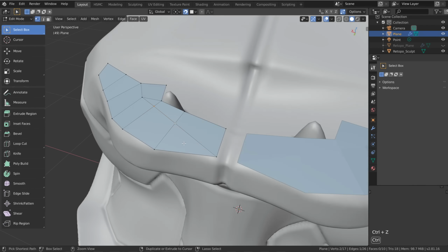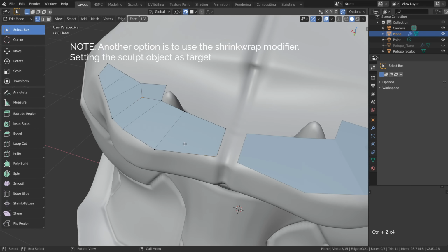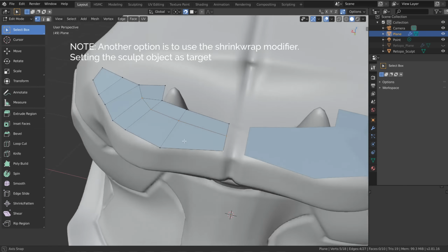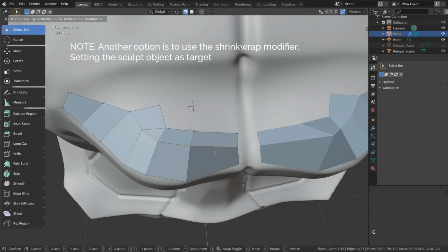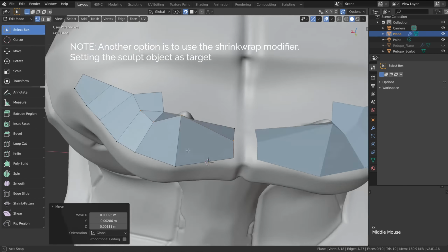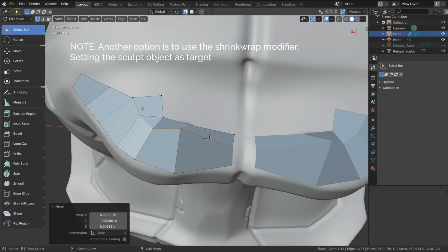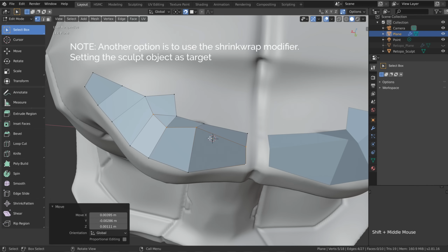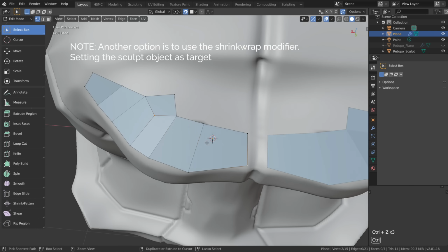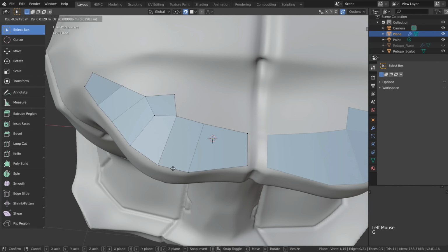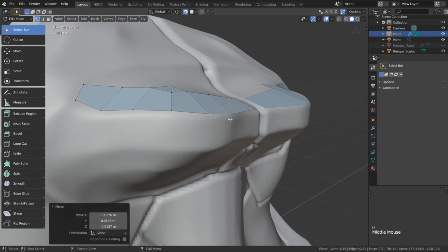Let's undo that a couple of times and now try the knife tool with K. I'm just going to cut from that vertex from here to here over to say in the middle of this edge and hit enter. Those vertices aren't conforming either until we press G. So with a bunch of the tools, it's worth being mindful of what we can get away with here, which is actually conforming to the surface. So let's just undo all that a few times and just know that hitting G at the end is probably the safest bet, just to make sure that we're definitely on the surface.